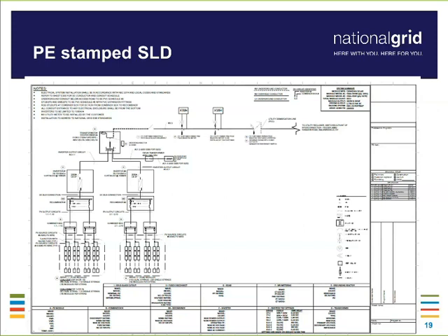It's a little small. But if you're utilizing resistance or reactance in the ground, we would need to see that illustrated as well as the details of that shown on the drawing. So we'd understand the impedance value of that device, its current values or ratings, and any withstand or short circuit values that it possesses would be information we would like to see on the drawings.